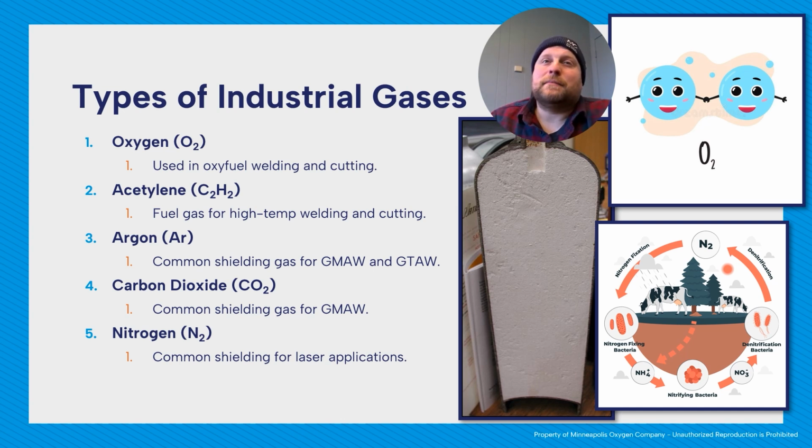How it was explained to me once, and I really like it, and let me know if I'm wrong, is that you can only use oxyfuel cutting if your material can oxidize at a high temperature. What that means is you're not really melting material. What you're doing is rapidly oxidizing in a very controlled way. What else is oxidation known for in iron? Rust. So you're kind of rusting in a very small, very controlled way, and then blowing out that rust, and that's kind of what your cut is, which is pretty cool, I think.